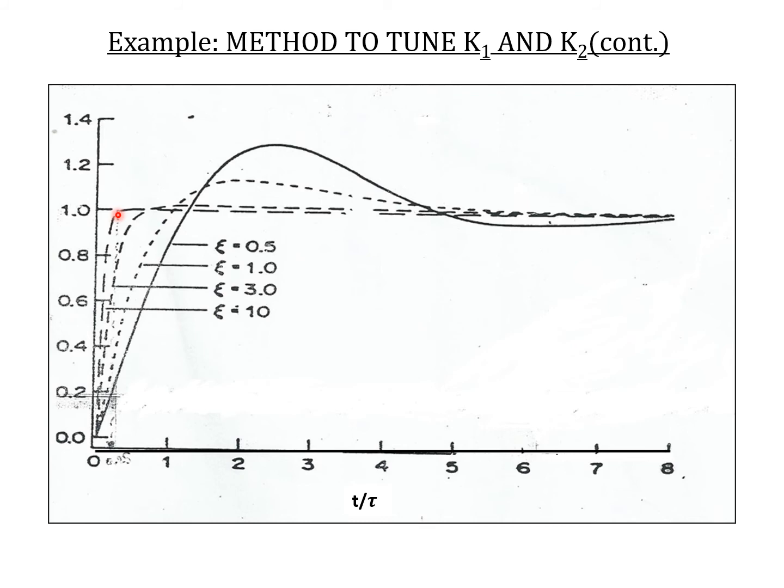It's an empirical method. But having those initial estimates, we can slowly fine-tune from there, not from just blind estimation, but with this sort of required estimation, we can get initial tuning, and from there we can fine-tune a bit. Of course, again, it depends on the zeta. We want a quick damping or a slow damping or an oscillatory response. It's up to us, we decide what sort of response.